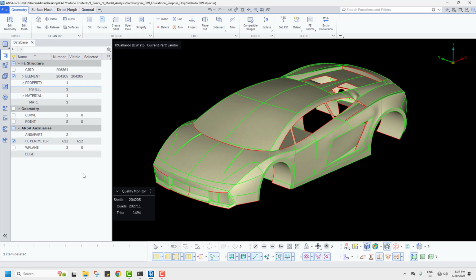at that time? If that is happening, then in the automotive industry we consider that there might be some connection issues in the model, or while defining the adhesives, the spot welds, or the nuts and bolts, or all the fasteners, you might have missed some. Due to that, the components might fly.